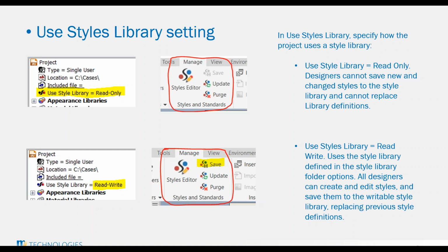What read-only means is basically you are having the user only work with what's in the design data folder. In other words, they can't make any changes. Say they have a drawing open and they needed a 4-place dimension style that was not currently there.